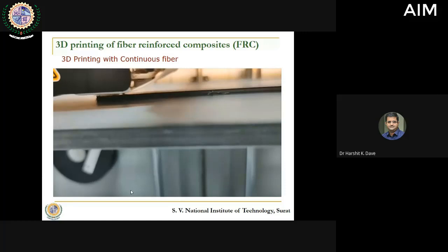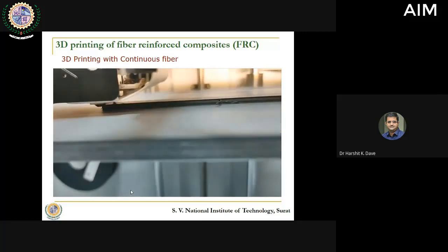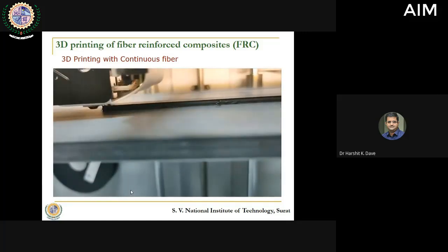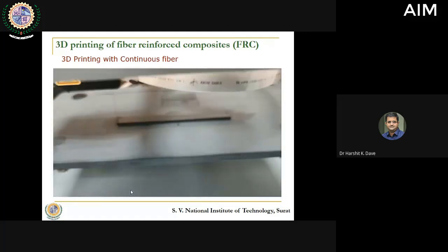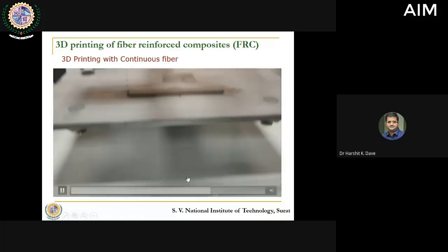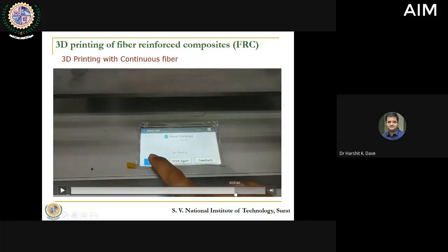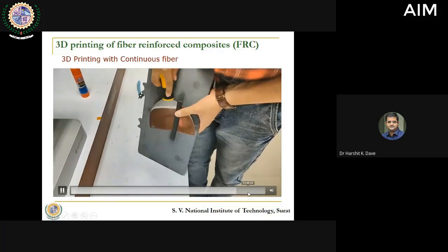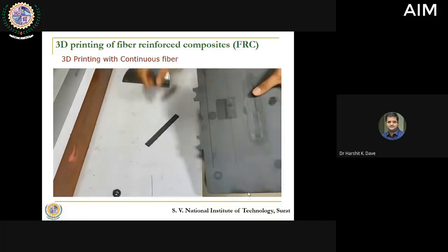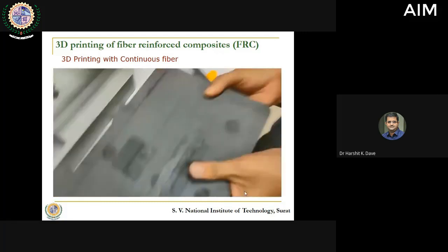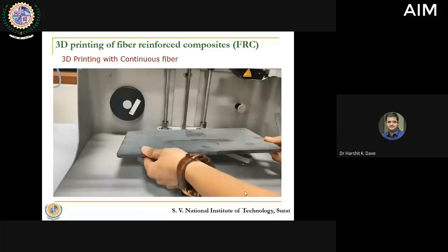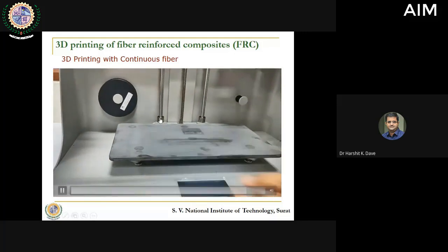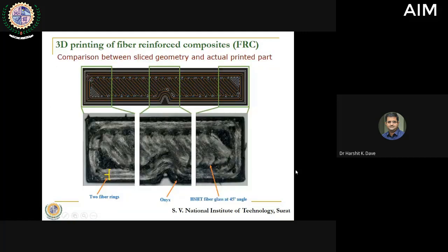So the entire structure is put up that way. Now you want to have a full layer at 45° for the filament. So that is how this layer is being printed. Then this is how it ends. So this part ends, and then you can separate the entire build form, and very easily you can remove the part. So the chances of any deformation in the part during this removal are greatly reduced, because as per your convenience you are able to remove it. So this is how the printing is carried out, and you can see the part that is printed.